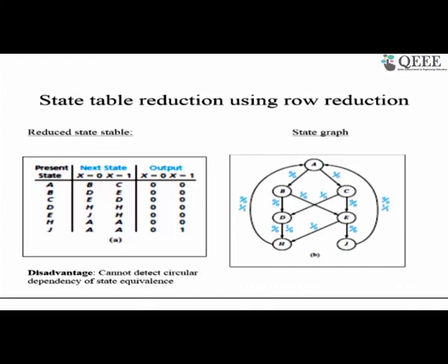That is called the truth table of the flip flop. In the case of an excitation table, we decide the excitation to be given to the flip flop for the desired transition to occur. For the given input and the desired next state bit to be stored, what should be the input to the flip flop? That denotes the excitation table.